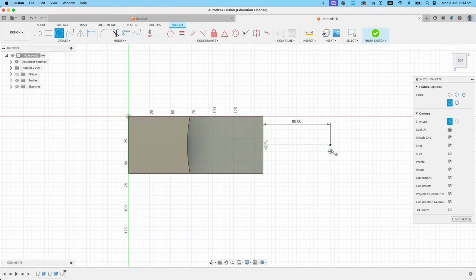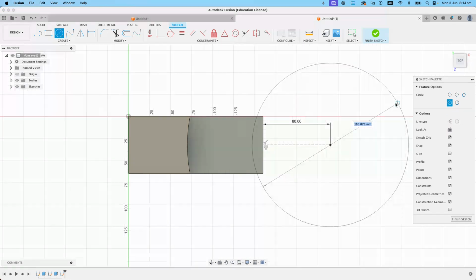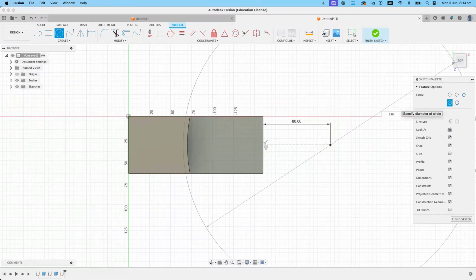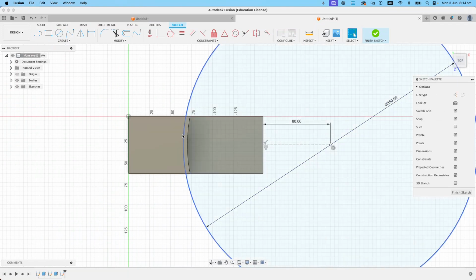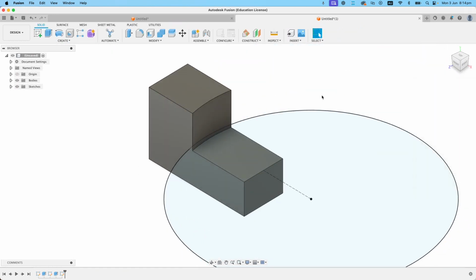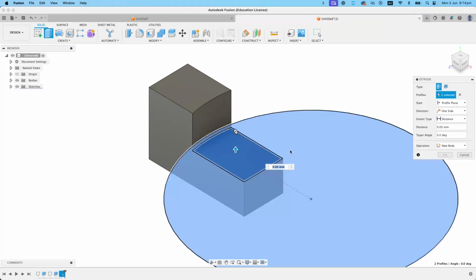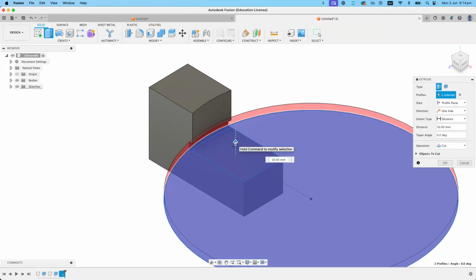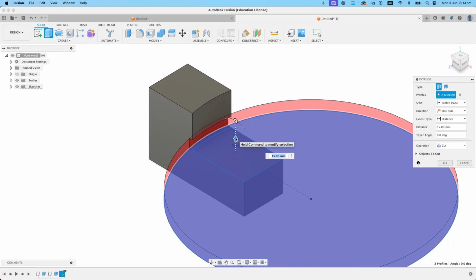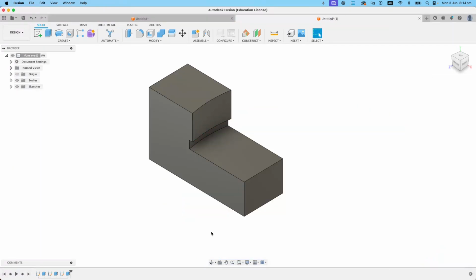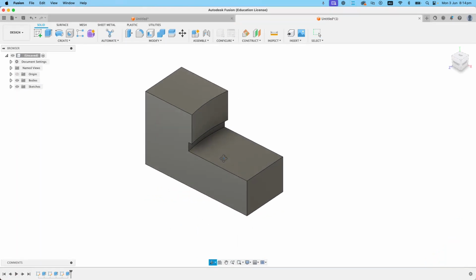And this time what I'll do is I'm just going to create a circle in here. Let's switch to that, and I'm just going to type in 350, and you can actually see that it's past this point. Let's finish the sketch. Let's see what happens here. All right, we are going to select that surface, both of those together, and I just use my shift key there. And what we're going to do now is extrude that upwards, and you can see it's going to make a cut. And when I look at my drawing, I can see that it's going to go 12 millimeters up, and that's just made that cut in there for us. Look at that, beautiful. All right, we are flying. Let's get the next part done. So if I bring my drawing back up, where are you, drawing? Not that one. Let's go.